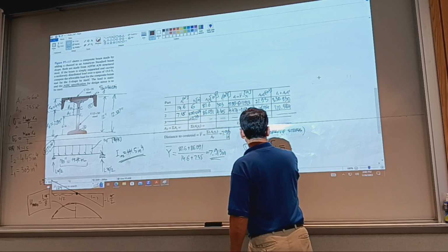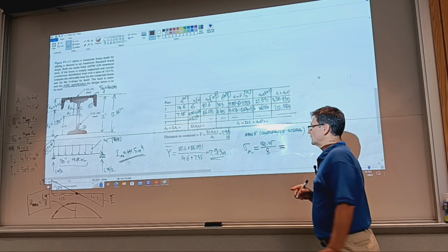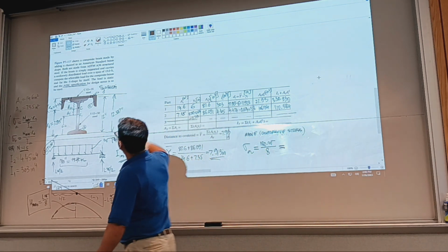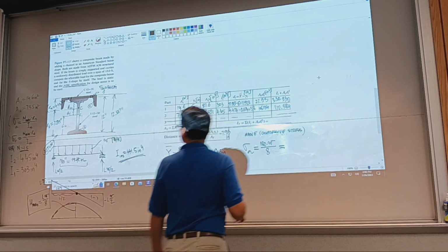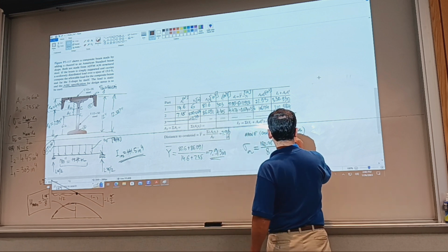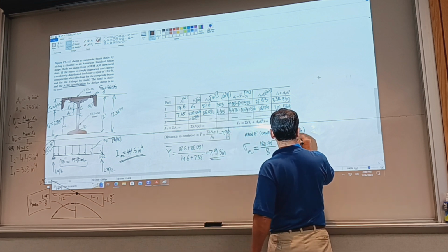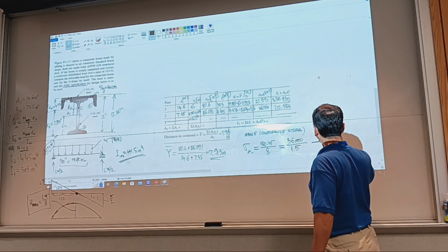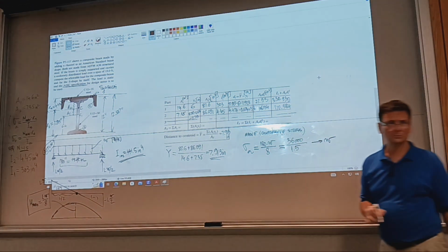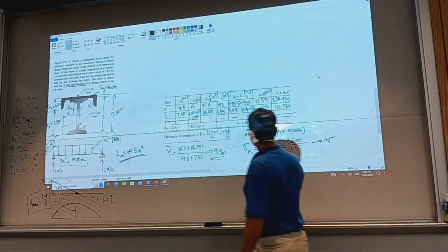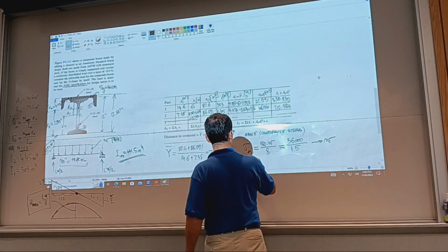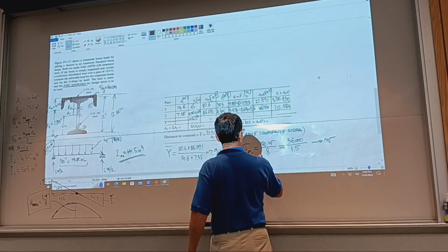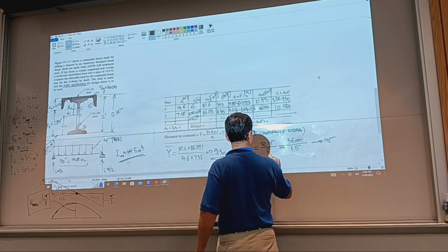So this will be the design stress equal to SY over design factor 1.5, so it would be 36,000 PSI over 1.5. We solve for the first W. And then I stay the same below, which is tensile.